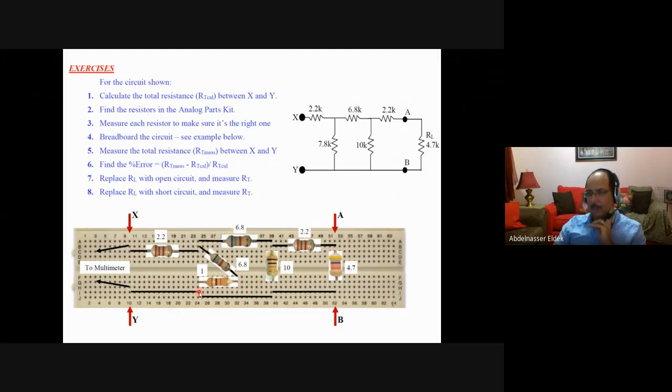Then another wire is connected between this node and the input node. Now these 2 points are the input of this circuit. Then you just connect these 2 points to the multimeter and set it to ohm, and let's see how it looks. I connected it already.